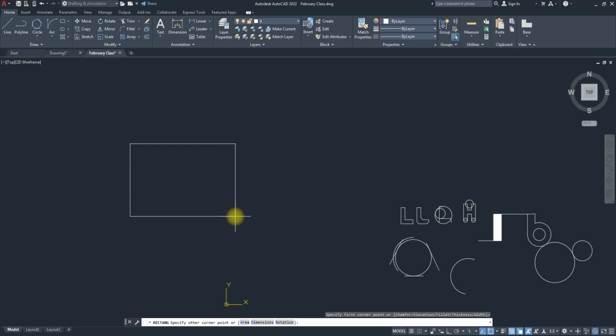So you just choose the dimension option. So I'll just choose the dimension, D for dimension. Then it's asking me for the length of the rectangle. So if I want to create a rectangle of length 60 and width maybe 45, it's asking me for length. I'll put the length 60, the width 45.